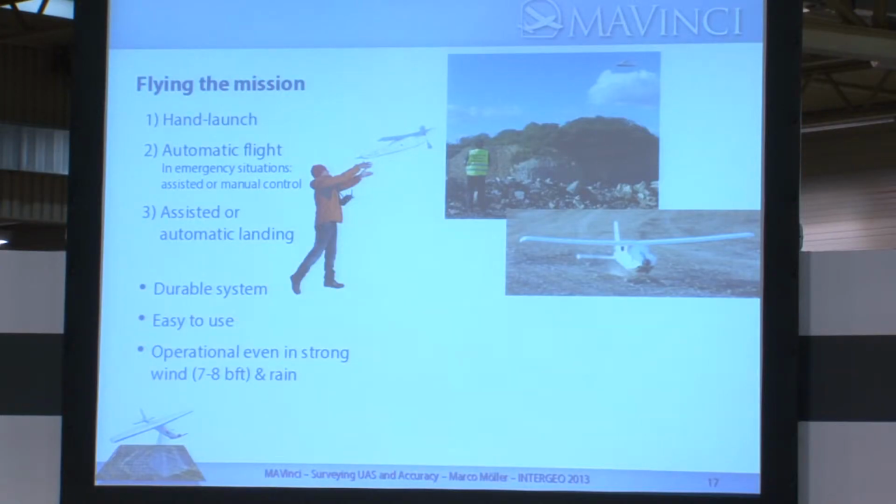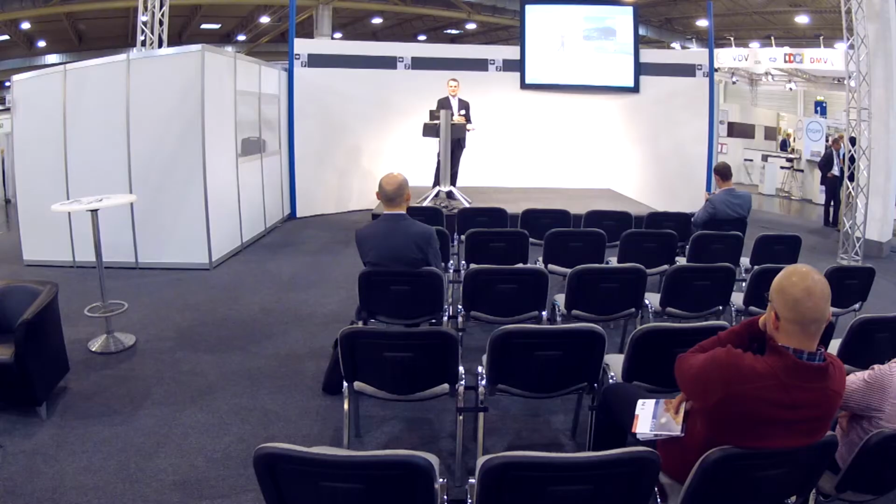So, another short fact about our flight is that we have a really durable system. It's a special foam material that's really strong against breaking, and if it breaks, you can glue it together again really easily. So we have really small spare part costs for you. We calculated about 18 euros for every landing, which also includes the battery, which is the biggest part, because normal UAV batteries will be end of life after 50 flights, because they are really lightweight and optimized to have high power and to be lightweight. So you have to reduce the lifetime, otherwise you couldn't achieve that goal.